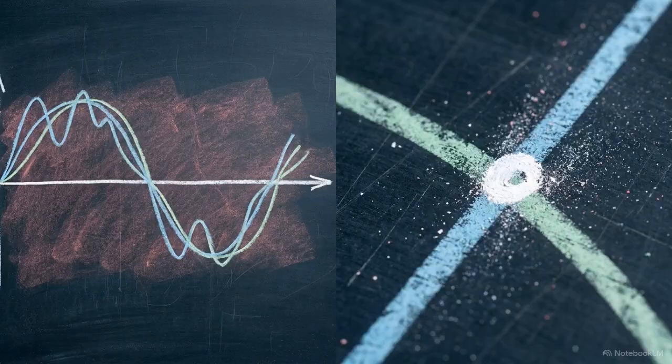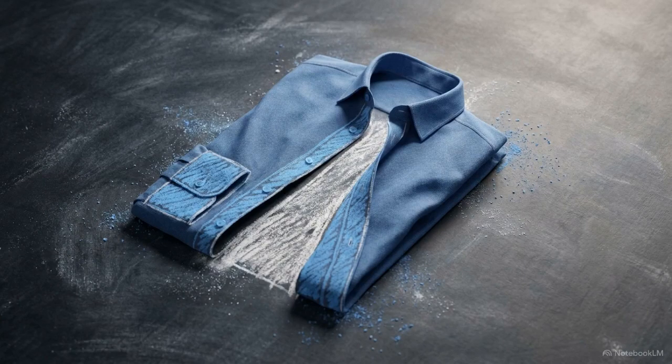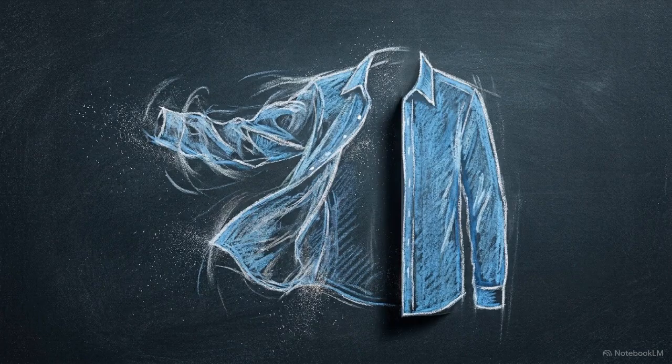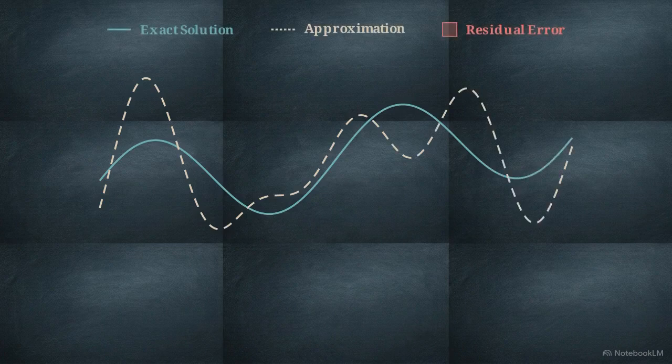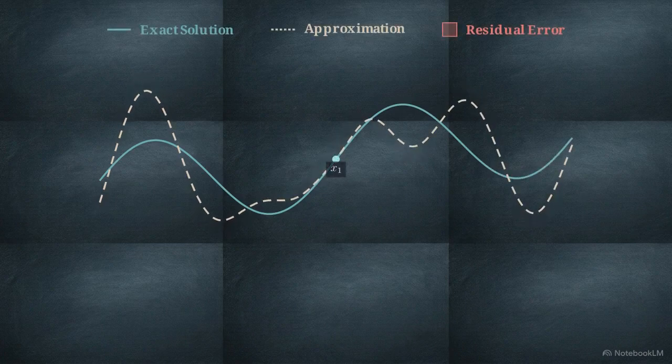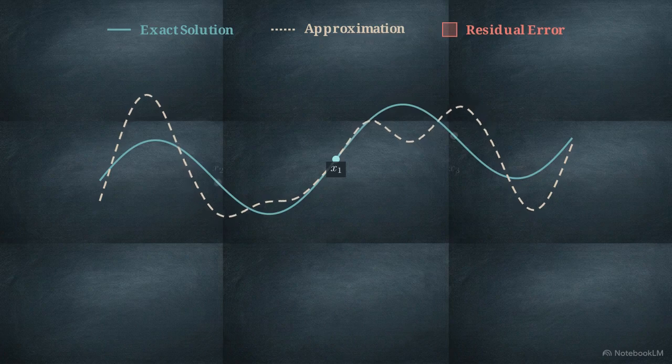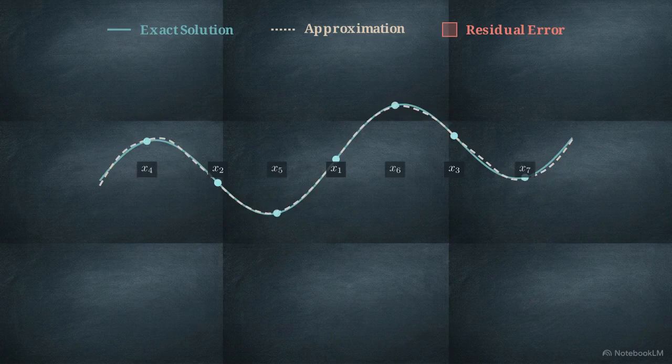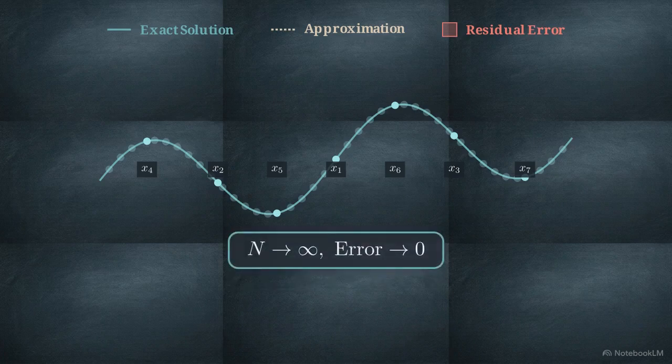at specific coordinates. Think of this discrete constraint physically, like aligning the two open edges of a shirt. If those edges have no connections, they move independently. In our math, that gap represents a massive error between the approximation and reality. Applying a single constraint forces the sides to meet at one exact coordinate. Space between still wiggles, leaving residual error. Increasing constraint points shrinks deviations. At the infinite mathematical limit, like closing a zipper, the approximation converges perfectly into the exact continuous solution.